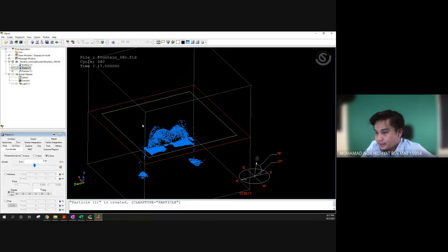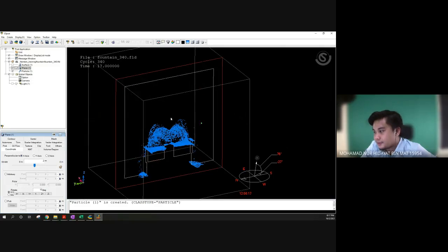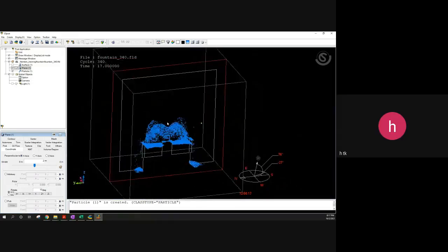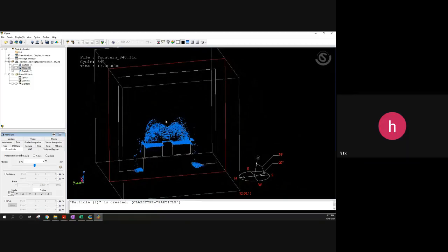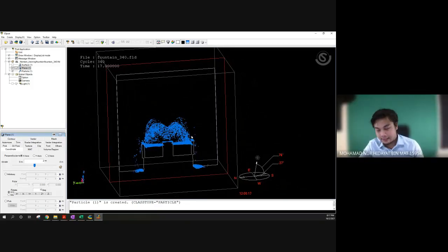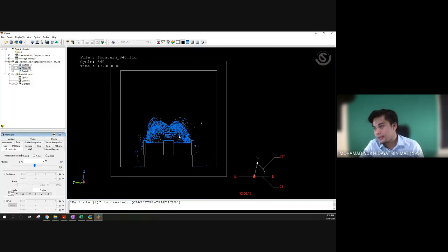So how to adjust my plane orientation? Go to the x axis. Can you see, this is the x? I want my plane perpendicular to the x axis, and draw it. Can you see? Press the A button on your keyboard. Okay, this is good.